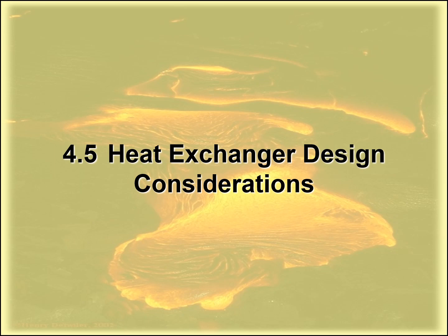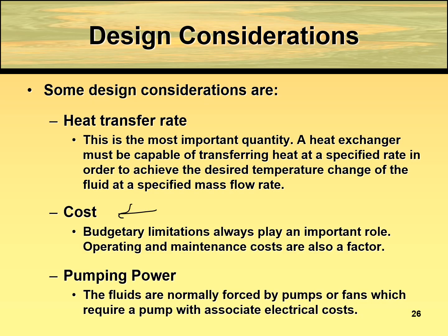And then finally, for the heat exchanger design considerations, you need to determine the rate of heat transfer required for that particular problem, and then what will be your budget, what will be your cost limitation, and the requirement for the pumping power that will determine the sizing of the piping system that you're going to use.